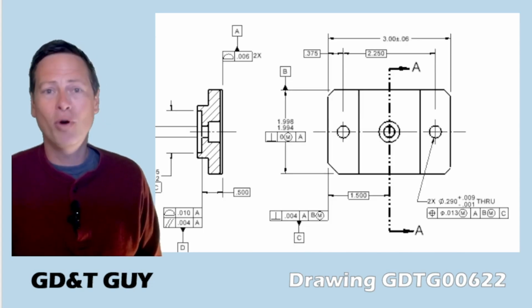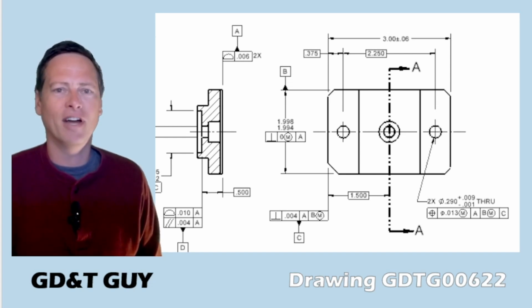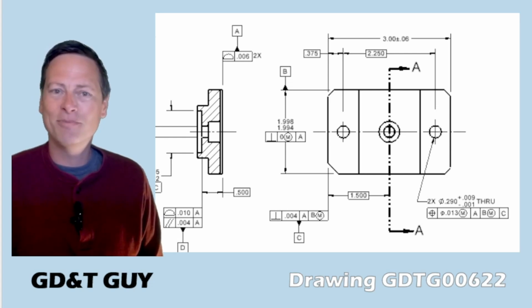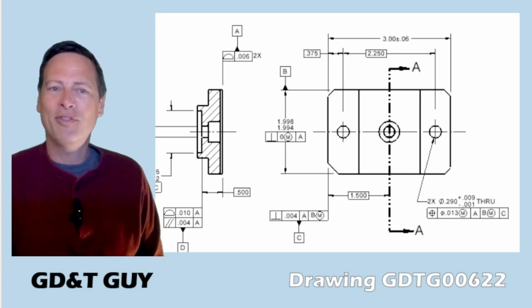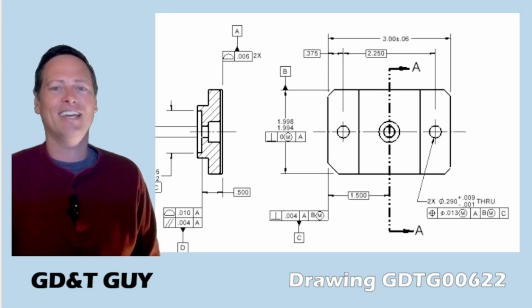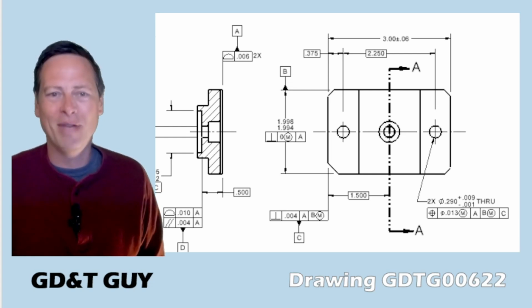So that makes it all the more important to control the perpendicularity of the datum C feature tighter than we may have otherwise done, because any angular deviation is going to project itself to the other side of the part, and possibly get worse because of the loose plus or minus 60 thousandths. So one of the ends, the datum C feature, has tight 4 thousandths control on its perpendicularity and form. But then the other end has what? Approximately 124 thousandths? Yikes. I hope you're able to follow that. Important points, but maybe not the main point.